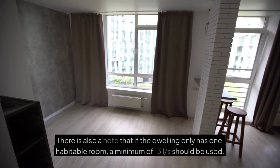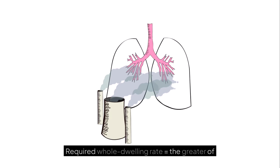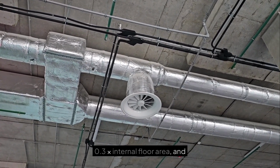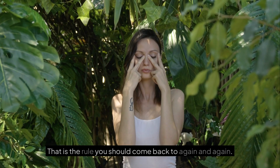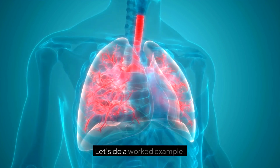The easiest way to teach yourself this is with a rule: required whole dwelling rate equals the greater of 0.3 times internal floor area and the bedroom-based minimum in Table 1.3. That is the rule you should come back to again and again. Let's do a worked example.